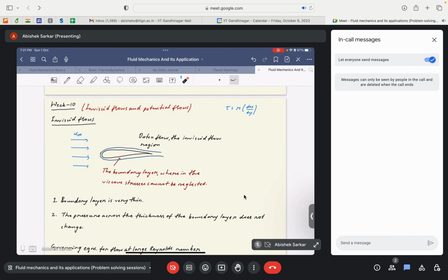And not only in the case of airfoils, but in most cases where the Reynolds number is usually very high, and that is actually the case for most of our day-to-day life flows, the boundary layer that will exist upon the object would be very, very thin. If the Reynolds number is high, then most of the flow physics around the body, which has its effect as the net resultant force on the object, the lift, is also because of the flow that resides outside the boundary layer.